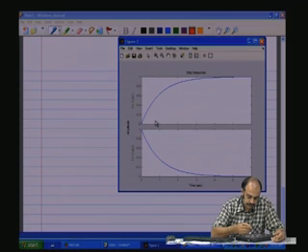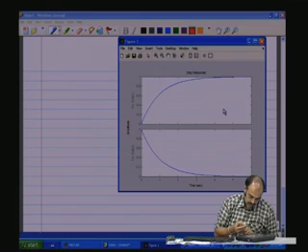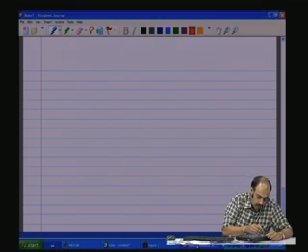And here, of course, we see that this is rising, and now when you remove the input, when you make it 0, you will see that this will decay, and the output will exist, meaning it will not be 0 even when the input is 0, and therefore, the gain will be infinite. So, the existence of the pole and the 0. So, let us just have a bit more consolidation on this pole 0 concept.